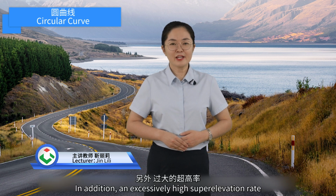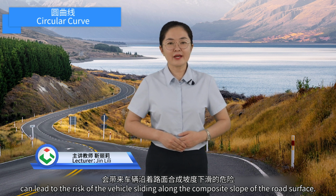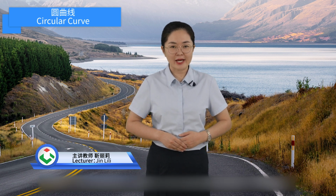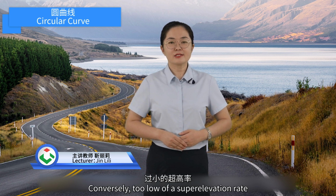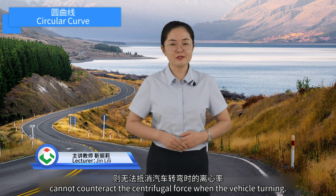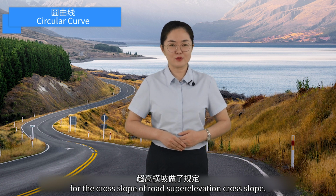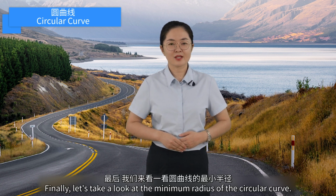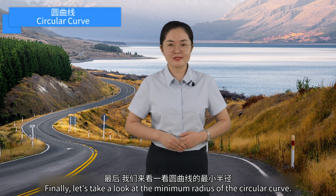In addition, an excessively high superelevation rate can lead to the risk of the vehicle sliding along the composite slope of the road surface. Conversely, too low of a superelevation rate cannot counteract the centrifugal force when the vehicle turning. Therefore, the specification also provides the specification for the superelevation cross slope of the road. Finally, let's take a look at the minimum radius of the circular curve.